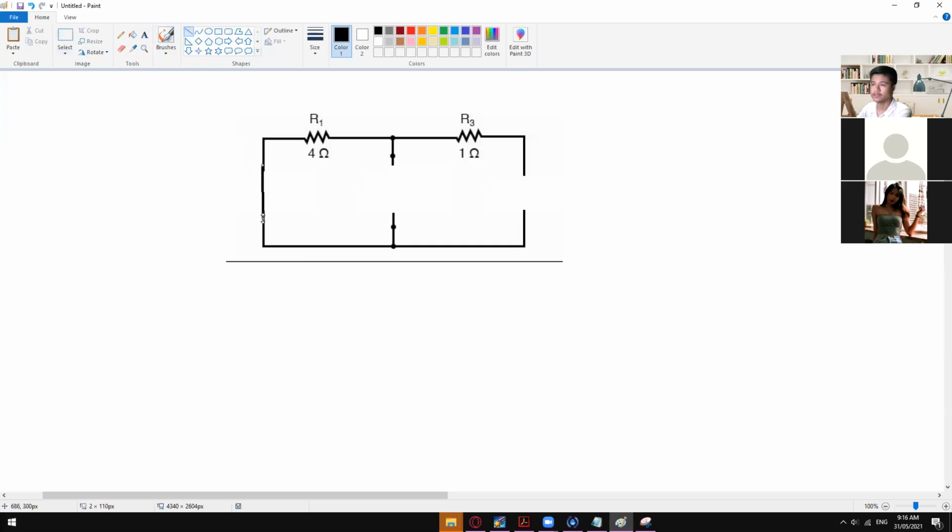Short circuit is one. And then we can now find the RTH right here, wherein this is now our node A, and then this is our node B. So looking for the total resistance across RTH, so we have to transform that one into this kind of circuit.